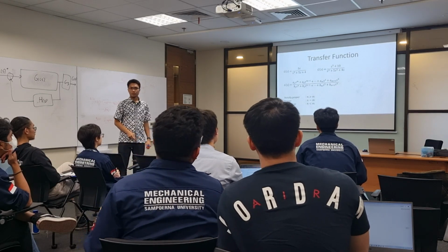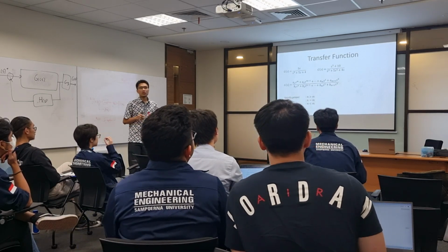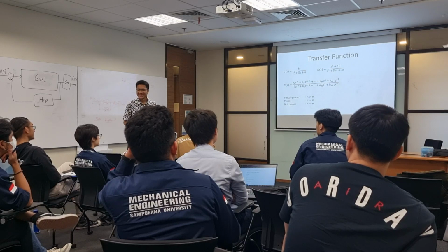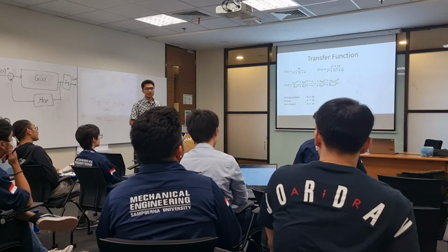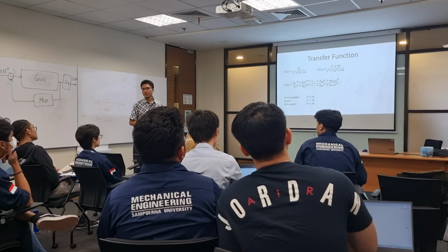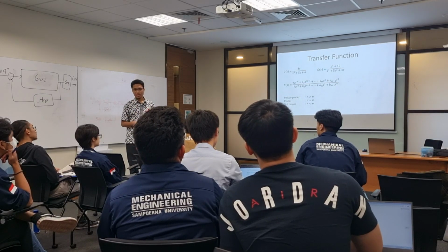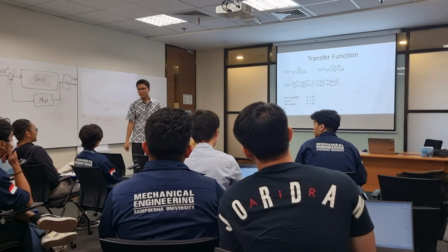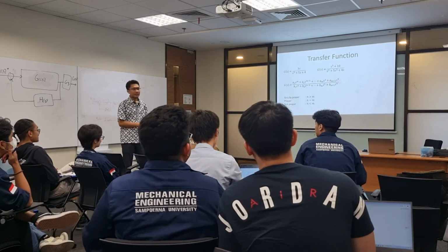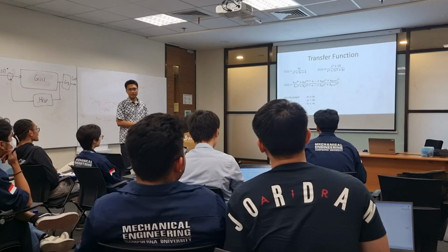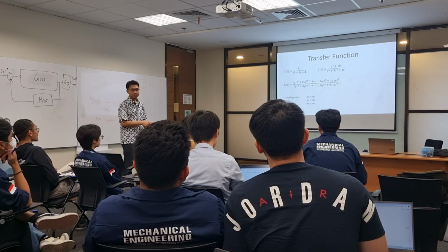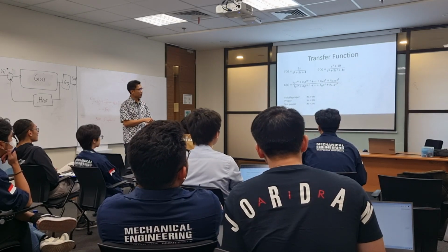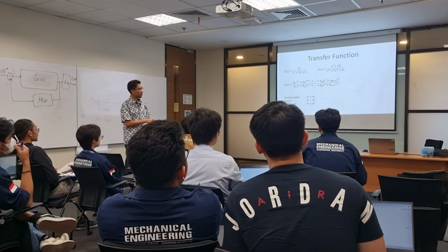The thing that I want to show you. I bet that you have never seen transfer functions a lot. Only a few times, right? In this class we should see a lot of transfer functions, and you will see a lot more in control. A transfer function has a numerator and a denominator in the form of polynomials. The transfer function is called strictly proper if the power in the denominator is greater than the power in the numerator.